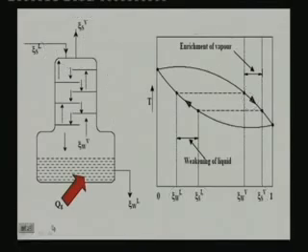One advantage of this particular system is that some of the heat is transferred from the hot vapor that is coming from the generator. And this heat is given to the solution that is going to the generator. That means the solution that is going to the generator is getting preheated by extracting heat from the vapor. This is beneficial because obviously this will reduce the required heat input in the generator. Otherwise, if this is not there, then the entire heat has to be supplied by the external medium in the generator itself. And this is wasteful, because ultimately the vapor has to go to the condenser, and the heat will be rejected in the condenser to a low temperature heat sink. So, instead of throwing it to the low temperature heat sink, you are extracting some of the heat from the vapor before it goes to the condenser. So this is good as far as the system COP is concerned.